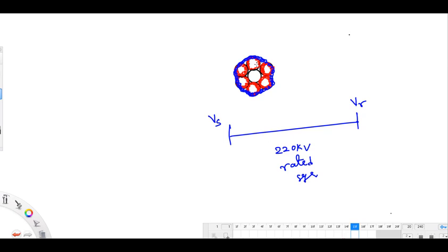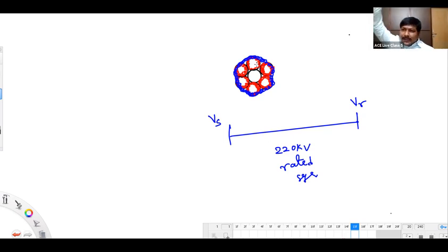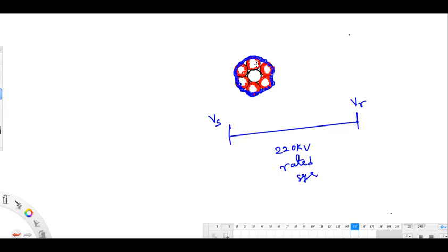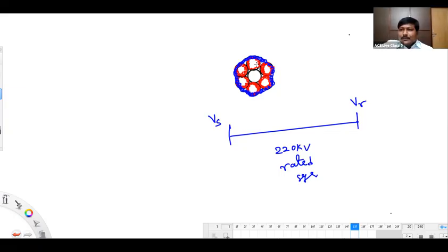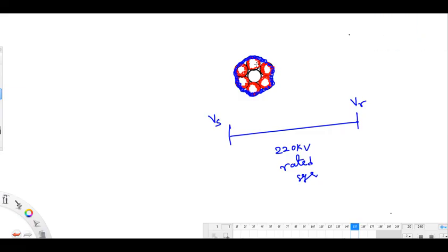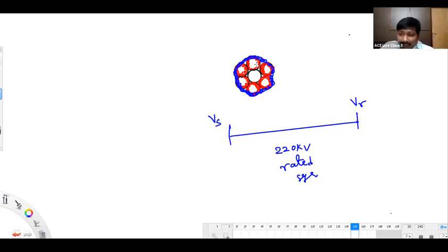No, sir. We keep that electrode deep down, not just on the surface of the ground. Even if we keep it just on the surface, current will not flow, because of the resistivity issue. So for better grounding, we should go for a deep length. Approximately, yes.